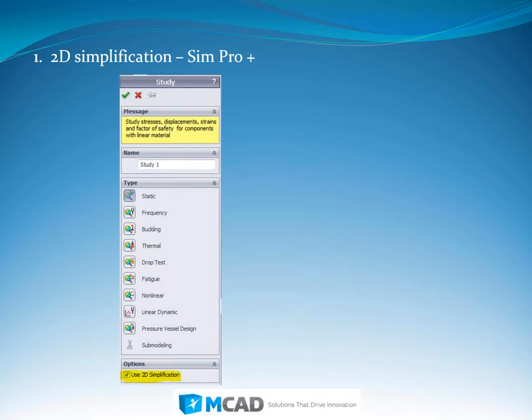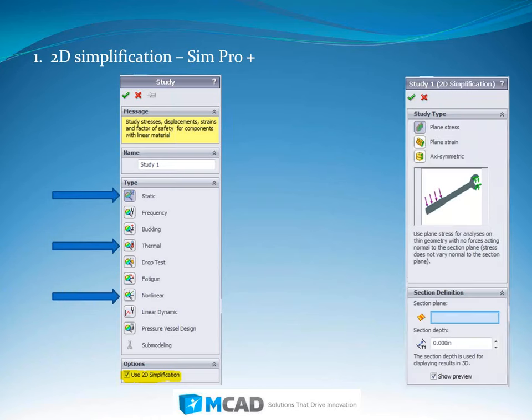So when we set up studies within simulation, if we have Simulation Professional, you'll see the option down below there for using 2D simplification. And this is available to us for static, thermal, and nonlinear study types. So all 3 of those can be mapped over to use 2D simplification.